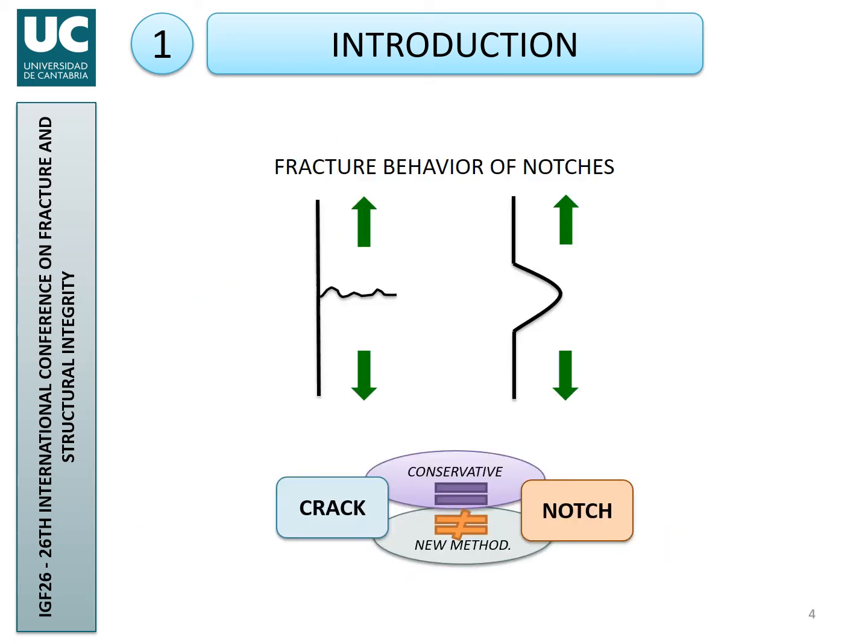However, we may have defects that are not crack-like, but we may have notch type defects, on which the main difference is that we have here on the tip a finite radius, generating less demanding stress fields on the tip. As a consequence, the apparent fracture toughness developed by the material in notched conditions is higher than the fracture toughness obtained in cracked conditions, and this of course affects the fracture resistance values obtained along the ductile to brittle transition zone.